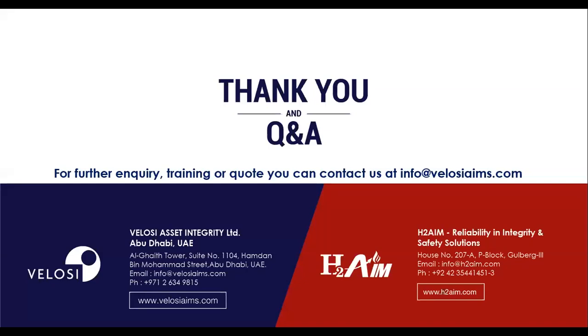Next question. Does NFPA specify inspection requirements for sprinkler systems? If yes, what is the frequency and method? See, this frequency is given in the NFPA, like yearly, bi-yearly, depending upon the nature of the system you are applying, and mostly companies are following it. There is a requirement of functional testing for a firefighting system. How to check the integrity of the sprinklers after years of no fire-related accidents? So functional testing is required. That is one of the purposes and objectives of functional testing.